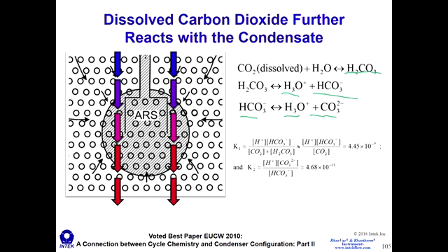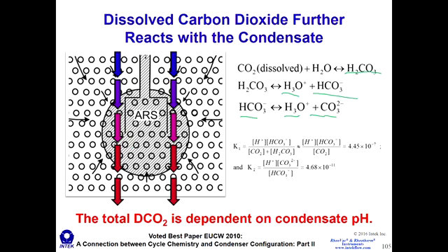And so all this while, the condensate pH is affected. It can dissolve corrosion in the condenser, cause corrosion particulates to get into the condensate. And this is a real problem. These airbound zones can be a real issue as far as corrosion and condensate chemistry throughout the cycle.